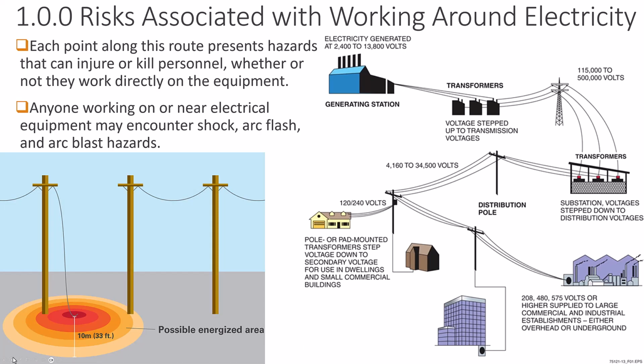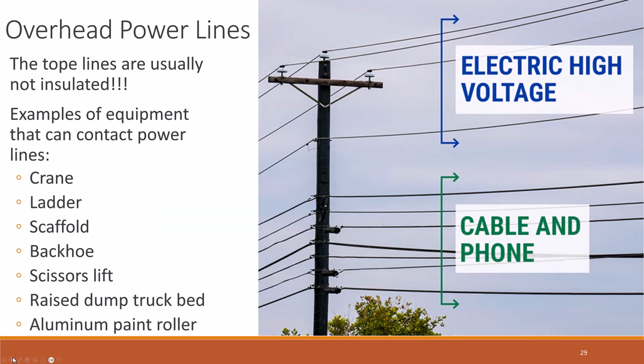And if a power line is cut down, maybe drops, gets broken because of a branch coming down, it can be touching the ground, touching a tree, and it can conduct through there and cause electrocution, even though you haven't touched the tree or touched the wire yet, because the ground can conduct it. So you've got to be careful about your distance and keep your distance. It dissipates the further and further away you get from the energy. You can kind of think of concentric circles from that wire emanating out, and how you've got to keep back and keep your distance.